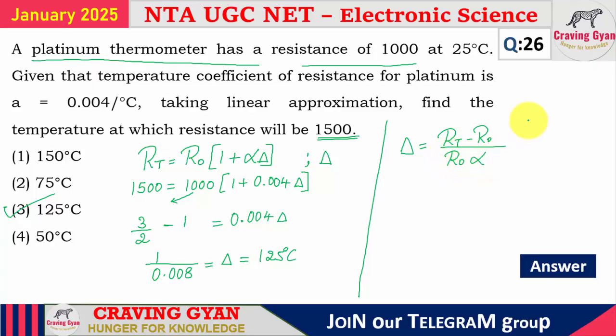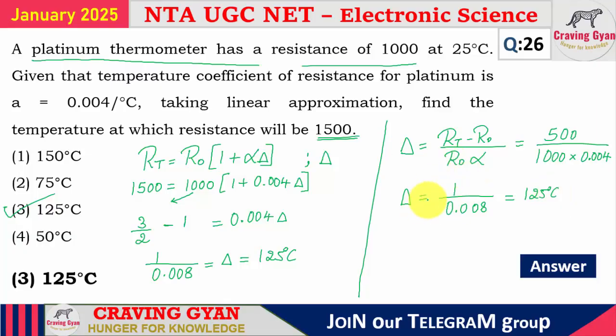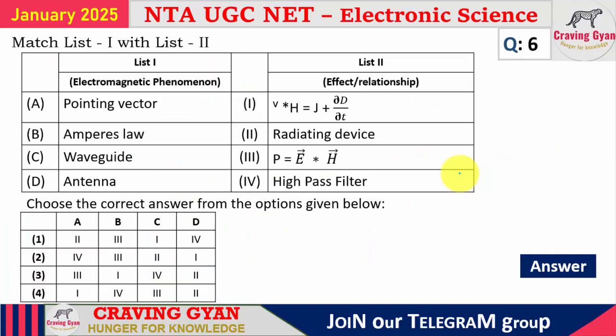This is another way to solve. RT is 1500 and R0 is 1000, so the numerator is 500, divided by 1000 into alpha, which is 0.004. 500 ones are 500, 500 twos are 1000, so delta equals 1 divided by 0.008, which equals 125 degrees centigrade. Option 3 is correct. Either you rearrange and substitute, or directly substitute and solve, you will get the answer.